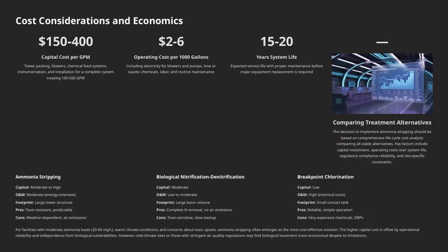Breakpoint chlorination is the least expensive to install, with low capital costs, but it has high operational costs due to chemical expenses. It requires a small contact tank and is reliable and simple to operate, but it involves expensive chemicals